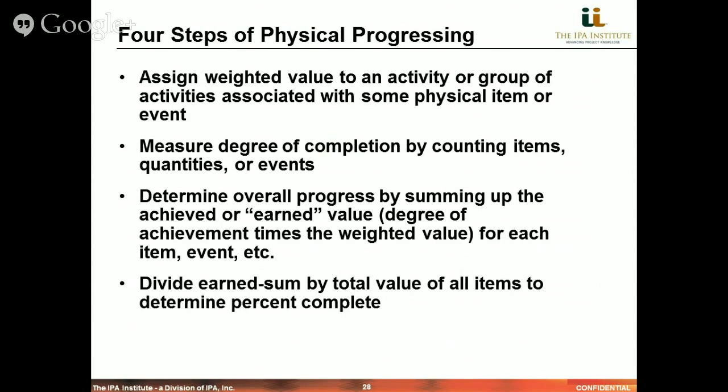After you've built your cost estimate and your quantities that are based on that, you assign a weighted value to an activity or a group of activities or deliverables associated with some physical item or event, whether it's installation of foundations in a particular area or completion of piping, or in design, a final review of some step in the process of design.